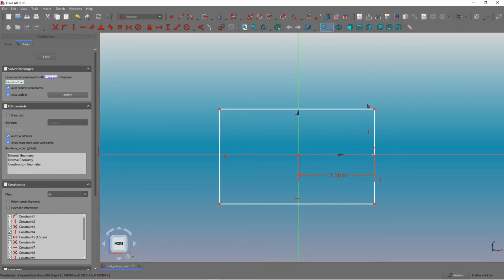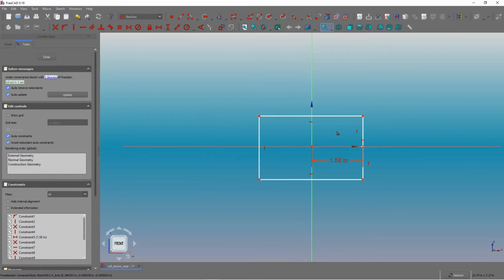So this looks decent, and then I want to put some constraints, make sure this is symmetric about the x-axis, and also symmetric about the z-axis. To do that, I'm going to use the symmetric constraint again. And so now, yeah, do the symmetric constraint here as well.